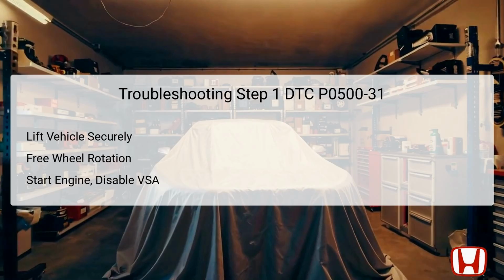After the vehicle is lifted, start the engine and disable the Vehicle Stability Assist (VSA) system. This allows for precise diagnostic testing without interference from other electronic stability programs, ensuring that you capture an accurate reading from the CVT speed sensor. Pay attention to the safety protocol while lifting the vehicle, as it's vital to prevent accidents during diagnostics.